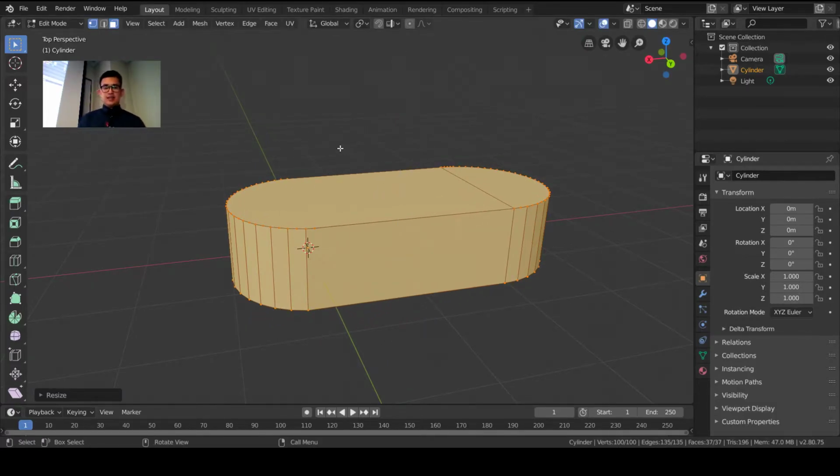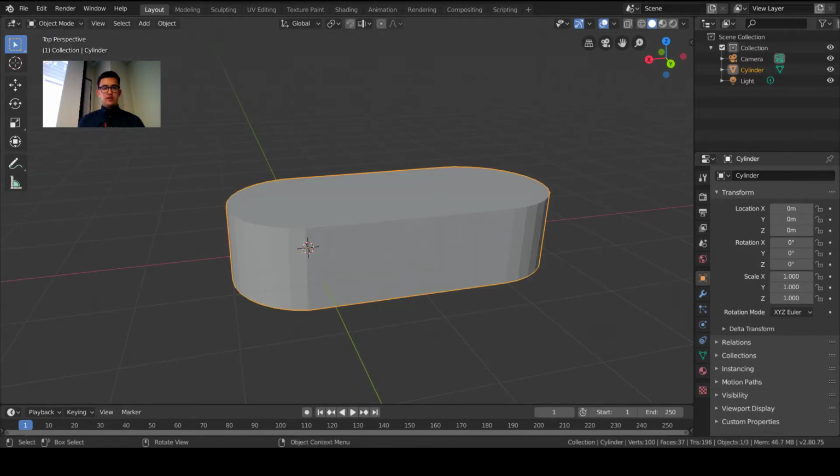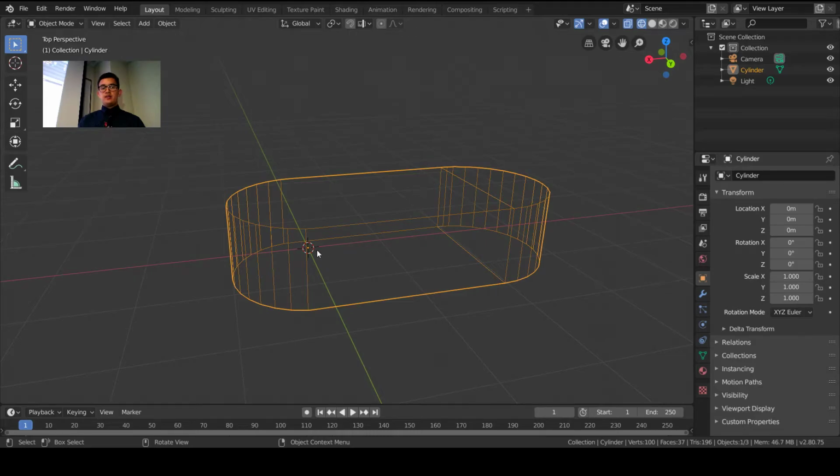Yeah, so that's that. And another thing I might want to do is get my origin fixed to the center of this. So let me deselect everything and go back to object mode. And if I click wireframe here, you can kind of see the origin of the world is more on the left side of my receptacle plug. But to move it to the middle, I can snap it back to the middle after. And let me show you how to do that.